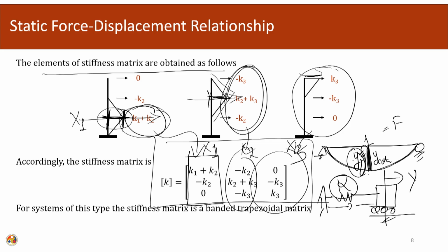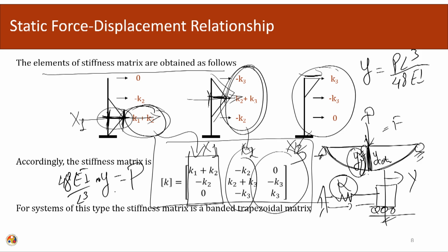As per the deflection equation, the value of y, let us say this is a loading P, is P L cube over 48 EI. So, 48 EI over L cube times y becomes P. So, if I am giving a unit displacement out here, if y equals 1, what is the amount of force required? It will be equal to this number.